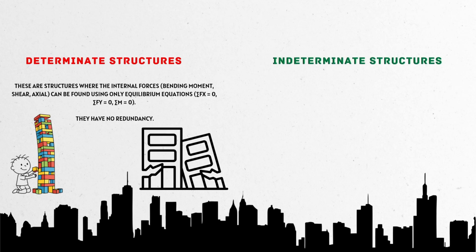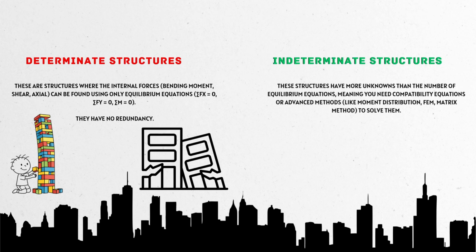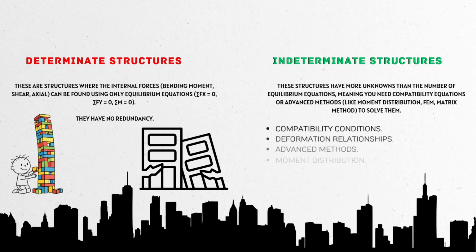Now, indeterminate structures. These structures have more unknown forces than the number of equilibrium equations. So equilibrium alone is not enough. To solve them, we need more tools. Compatibility conditions, deformation relationships, and advanced methods. Moment distribution, matrix method, finite element method.